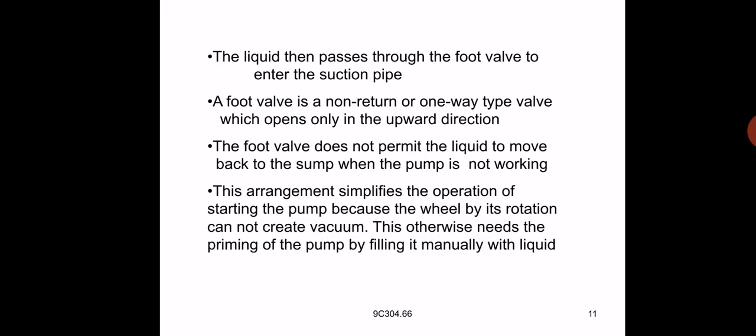This arrangement simplifies the operation of starting the pump, because the impeller by its rotation cannot create a vacuum, otherwise it needs the priming of the pump by filling it manually with the liquid. If you use the foot valve and strainer, priming is not required in a pump.